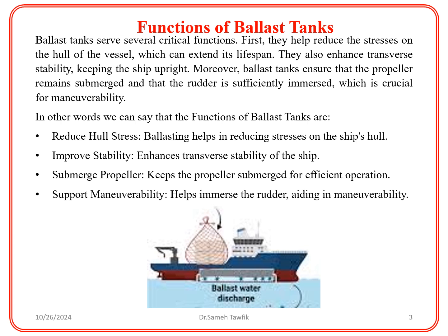Ballasting helps in reducing stresses on the ship's hull. Improve stability. Enhances transverse stability of the ship. Submerge propeller. Keeps the propeller submerged for efficient operation. Support maneuverability. Helps immerse the rudder, aiding in maneuverability.